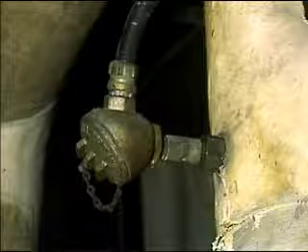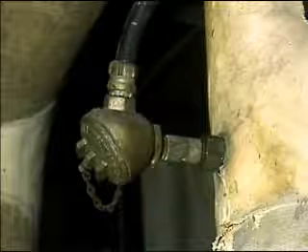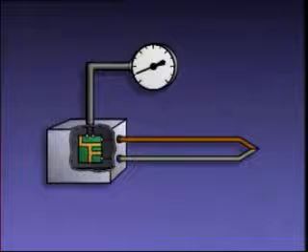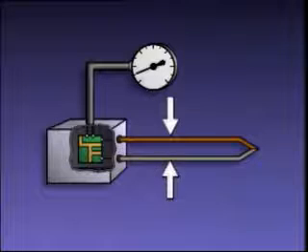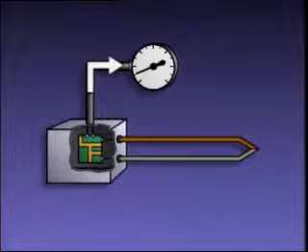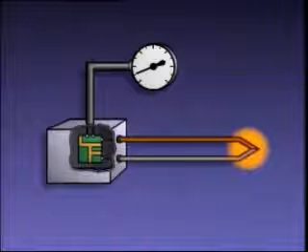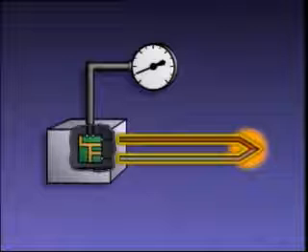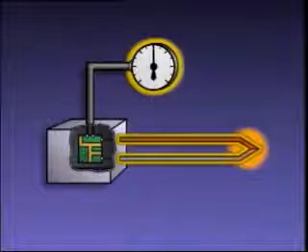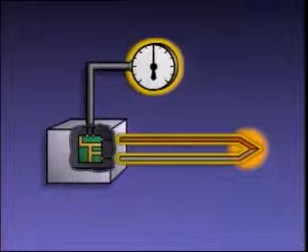While many temperature indicators are mechanical devices, some, like this thermocouple, are thermoelectric devices. They convert heat into electricity to measure temperature. A thermocouple consists of two wires of different metals joined at one end. The opposite ends of the wires are connected to an electronic circuit, which in turn is connected to an indicator. When heat is applied to the joined ends, a small voltage is generated in the wires. The electronic circuit detects the voltage and converts it to a corresponding temperature indication.